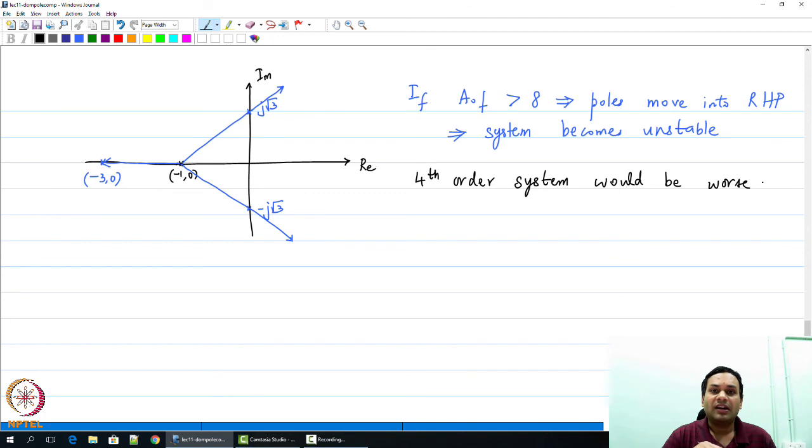Now let us regroup again, to give a recap of what we have been studying so far. We want to increase loop gain so that the steady state error of the system is extremely small, so that it's as close to 1 over f as possible, which is the ideal gain. Now it turns out that the first order system is unconditionally stable, so I'll summarize it here.